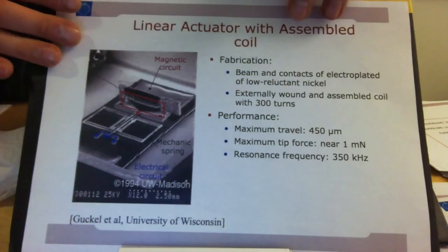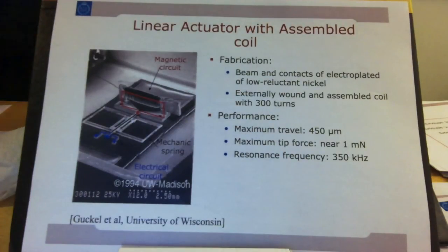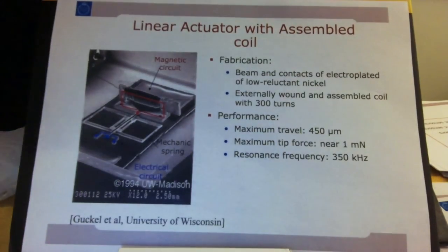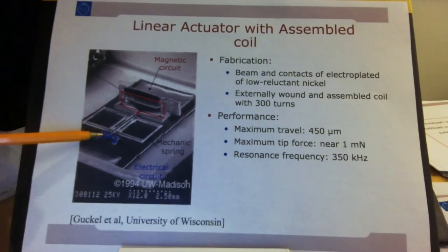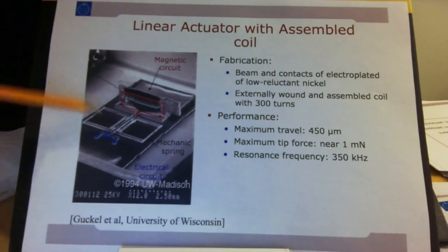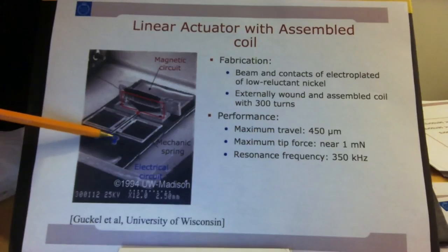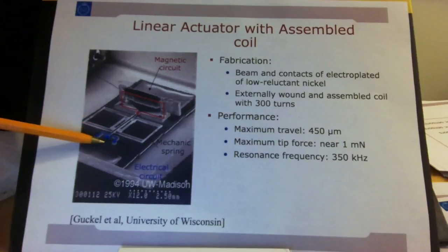It's a rather old example that we can see here, but still it's a good one. It's very pedagogic to show it. This is a relay, an electrical circuit switch. And what we're trying to do here is switch between these two poles. So we have an input port and an output port, and they're not connected. However, there's a moving bar here in between with a T structure, and if this bar is moved this way, the electricity will be able to connect through here to the bar and back here. But if the bar is pushed out, there's no electrical galvanic connection, and therefore the circuit is open. So if it's pulled in, it's closed. If it's pushed out, it's open.